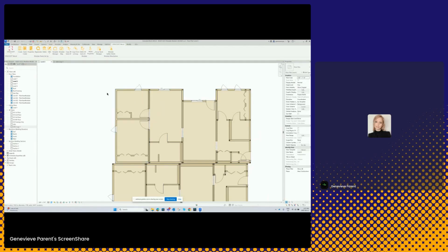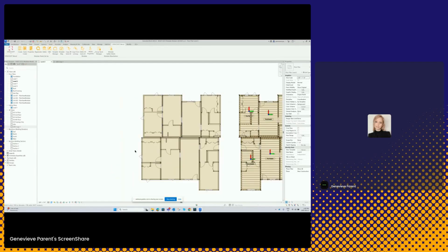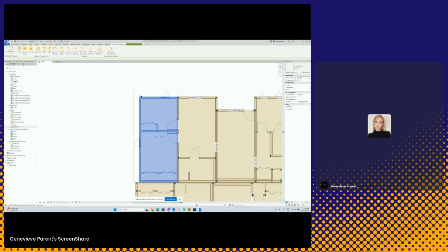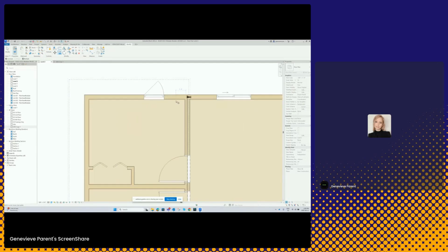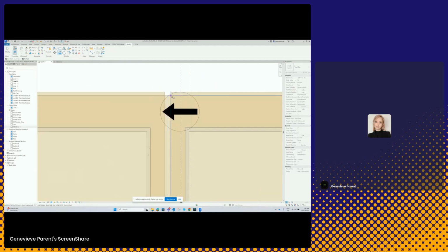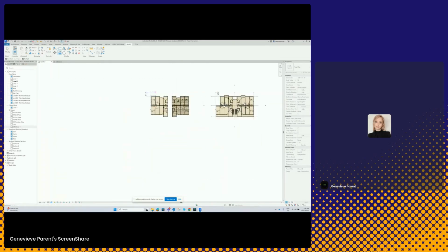First thing you're going to want to do with this is copy your groups over before you start adding your joins in the parent groups. So in this case, I am just going to copy this one over. And I'm going to use this reference point right here just because I know where it already is.